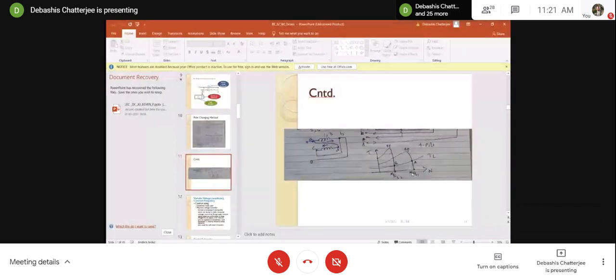Otherwise there will be a difference of synchronous speeds, and then the average torque over a complete cycle will be zero. But in cage machines, the rotor is of cage type, with bars and end rings, and the rotor conductors carry current in such a fashion that they assume the same number of poles as the stator winding. So we did not have to bother about it.